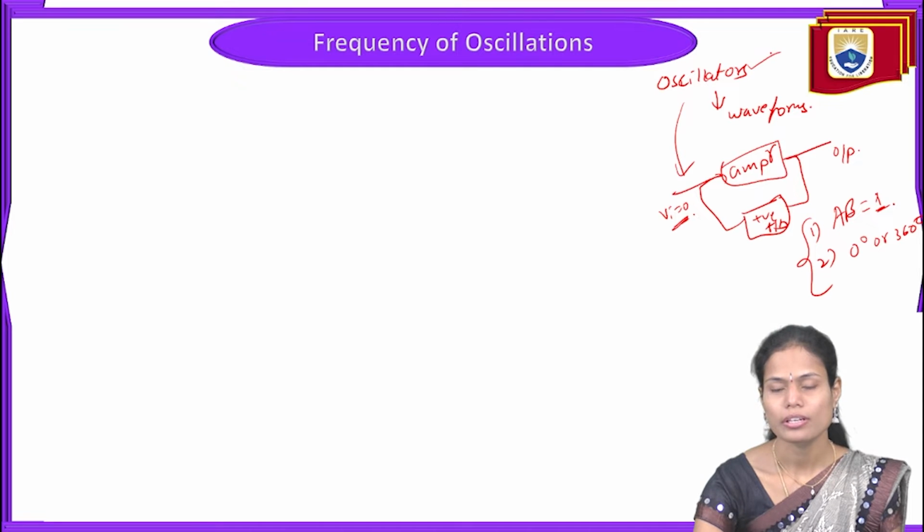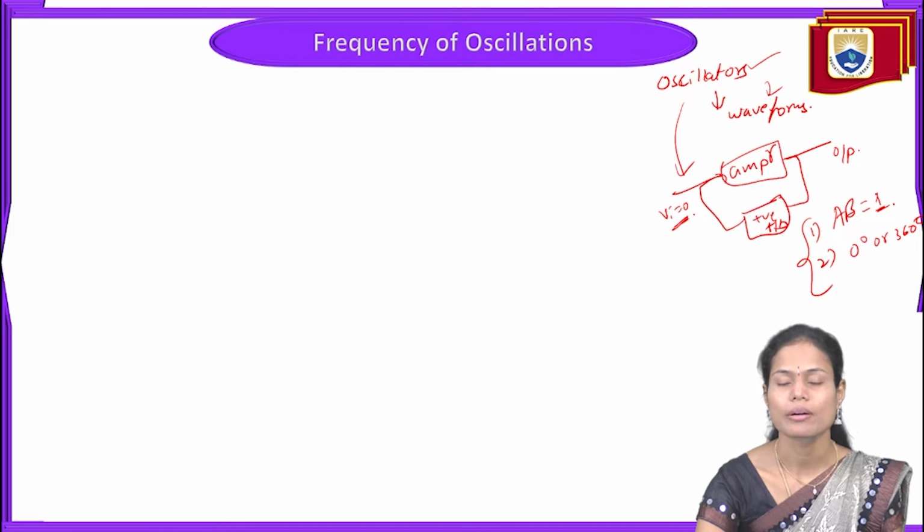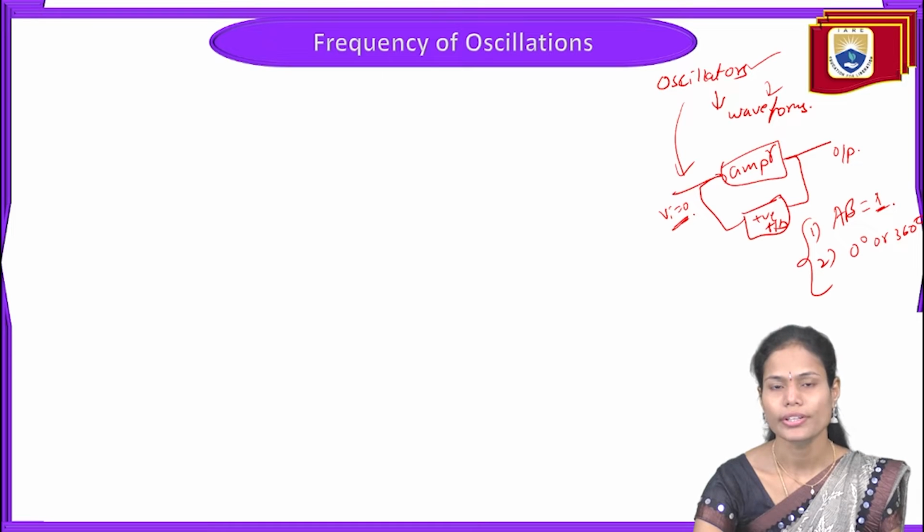These oscillators are available in different types, utilized to generate different types of waveforms, either sinusoidal or non-sinusoidal. In the case of sinusoidal waveforms, it will generate a sinusoidal signal as well as a cosinusoidal signal as the output. The RC phase shift oscillators come under the sinusoidal oscillators. As the name itself indicates, RC phase shift oscillators are designed with resistors and capacitors. The amplifier is common in any kind of oscillator circuit.